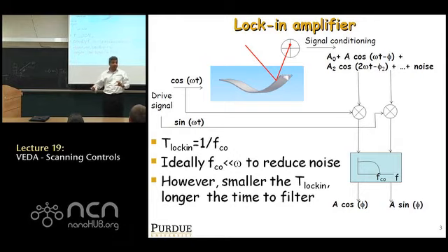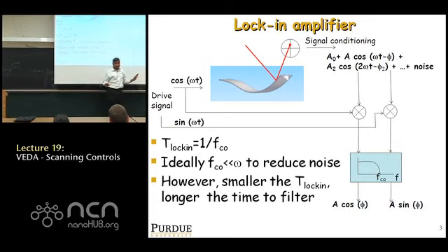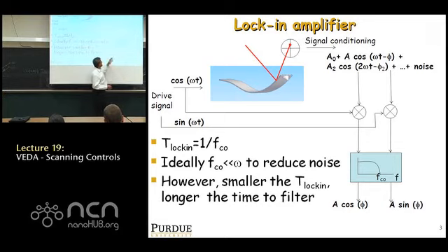Up to a certain cutoff frequency, fc, it allows all frequencies to pass through. Beyond that, it attenuates the signal completely. As a result, when you pass this product signal through a low-pass filter, you end up getting basically the term that multiplies cosine omega t in the signal.